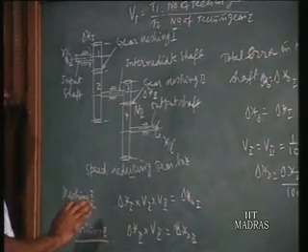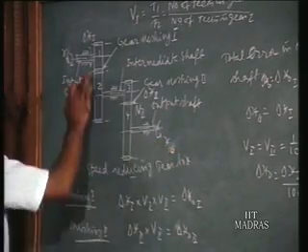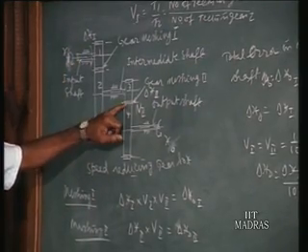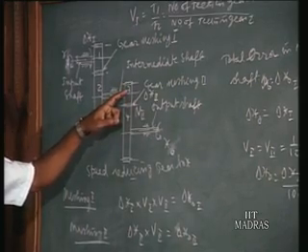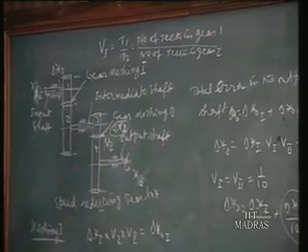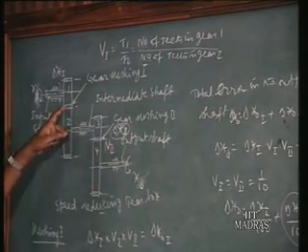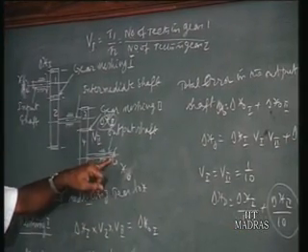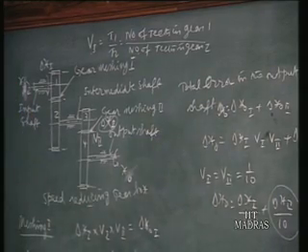So now if you eliminate the backlash, for example in the speed reducing unit, with xo and xi, since the major error comes from the last gear meshing, make one of the two gears a spring loaded scissor gear. Then you will not have any backlash there, and only the error in the output shaft will be from gear meshing 1, which is already divided by 100 times. So the net effect on the error in the output shaft will be very, very small, negligible, and such an error may be tolerable in many instrumentation applications.